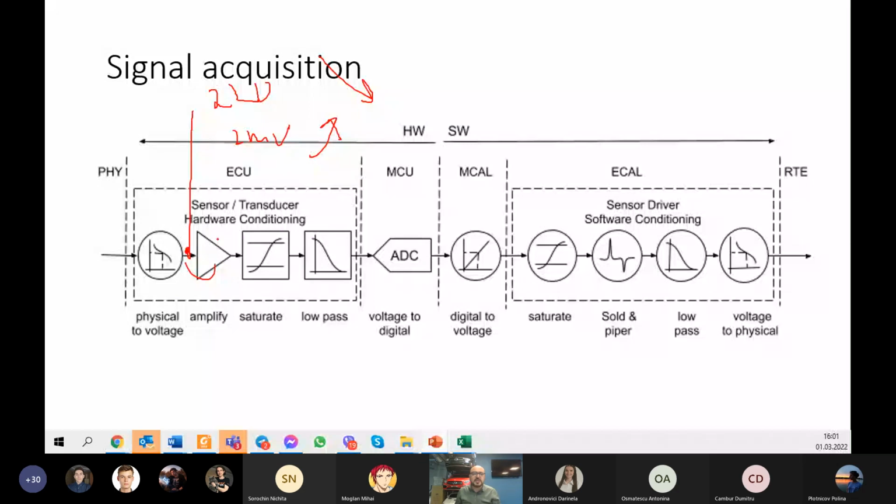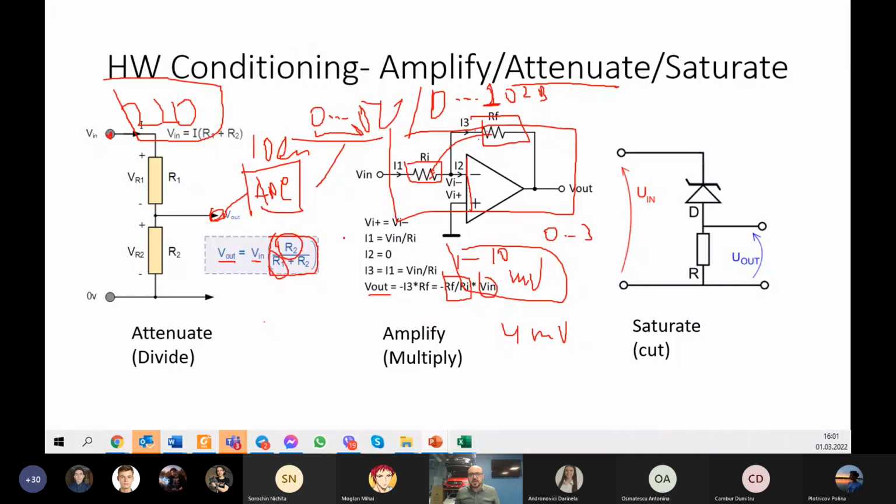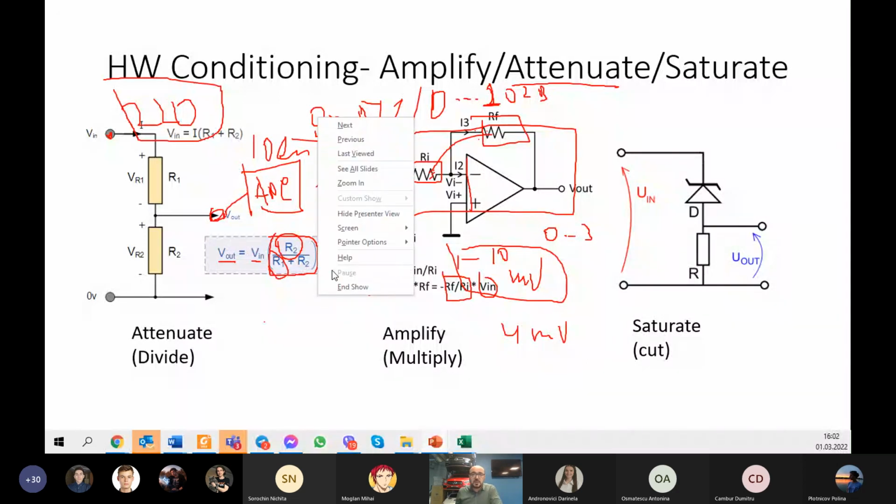And how are we doing that electrically? The sensor is converting, somehow mechanically, everything to the voltage domain, because all our state-of-the-art devices are electrical. So first of all, we should convert it to electrical. After that, having it inside our device, we should condition it in order to be in the range of the ADC. So how do we do that? Simply by amplifying or attenuating it.